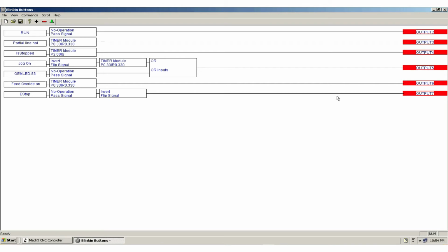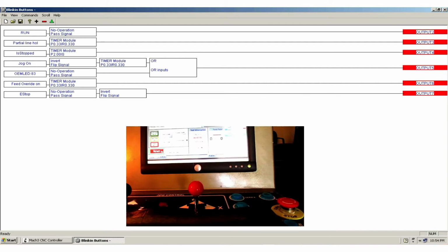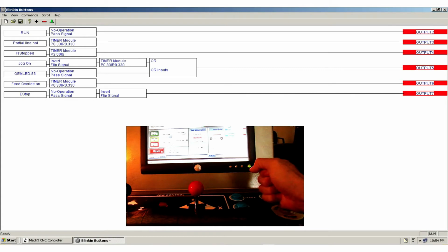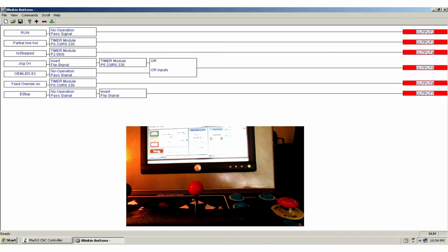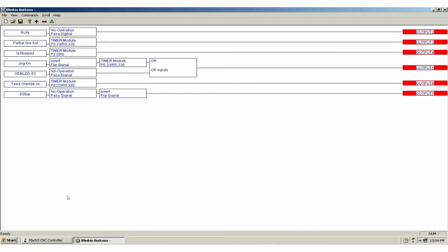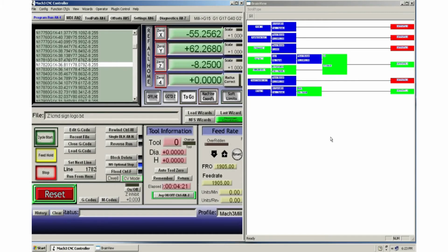Immediately Mach 3 shuts down all output signals. All LEDs turn off. The screen reset LED starts to flash when an external stop is requested, either by the E-Stop switch or a limit switch. So if you try to reset it, it won't do it unless the E-Stop switch is restored. Once it's restored, the brain turns it on again, but the screen button will flash until activation is performed by clicking on it. Now we have to resolve the turn on the real LED and the blinking action in our next part. Here's the brain that we just created.